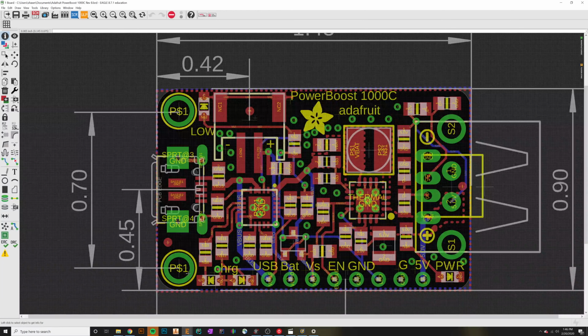So to add in the symbol, you're simply going to hit this button right here, the add tool, and there should be only one symbol, which is the one we created, and I'm just going to place it on the crosshair, just like that. Alright, and then in here, I'm just going to hit new, and then add local package. Okay, I'm going to find that exact package we just created and hit OK.